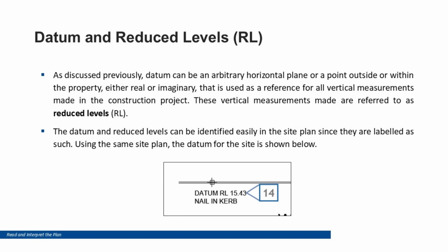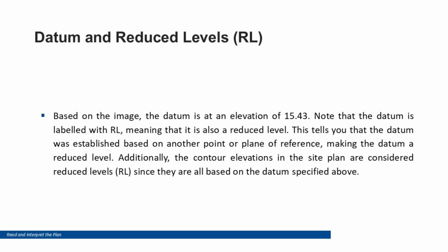You will also encounter reduced levels, RLs, which express height relative to the site's datum. This information is critical when setting out the building, planning cut and fill works, positioning drainage systems, and ensuring compliance with flood level requirements. Accurate interpretation ensures you avoid drainage issues, retaining wall failures and construction errors related to slope.